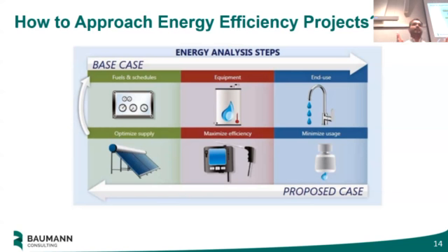Once you develop a baseline case, baseline here refers to creating a virtual model of the property that you are doing an audit for. Once you develop a baseline case, the next step in the process is to calibrate the model. Suppose this space has an energy consumption of 100,000 kilowatt hours. You need to ensure the virtual model you are preparing is within plus or minus 10% of the actual consumption. That is where we do the calibration.